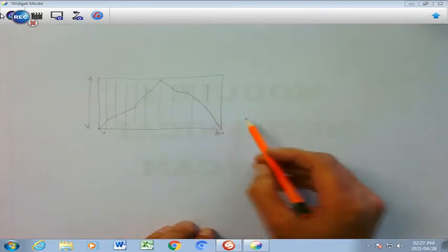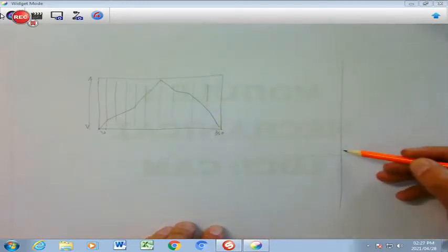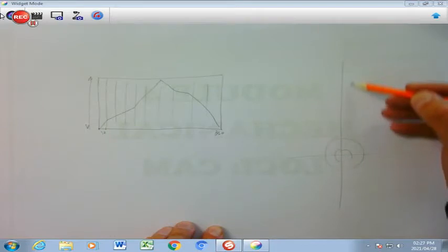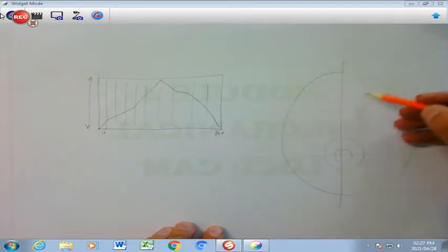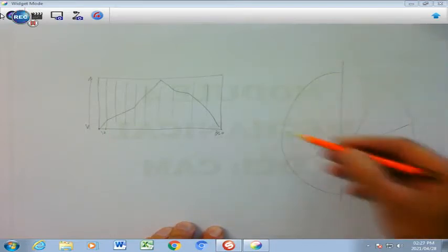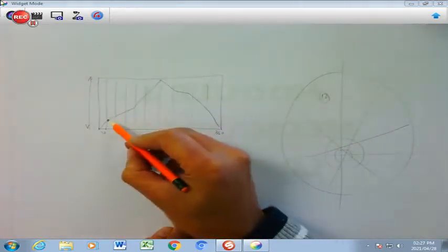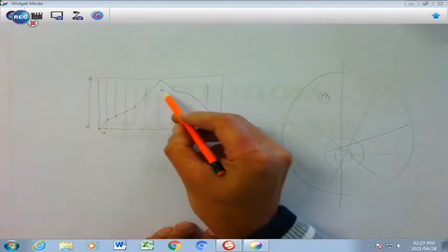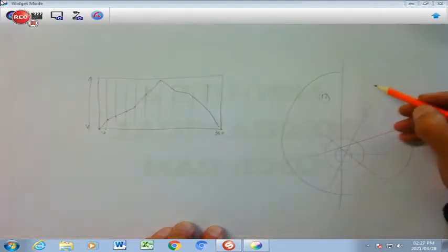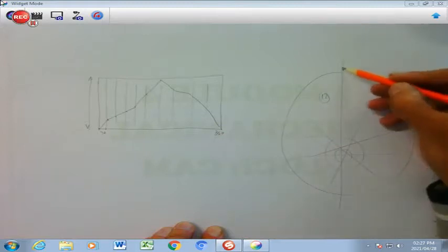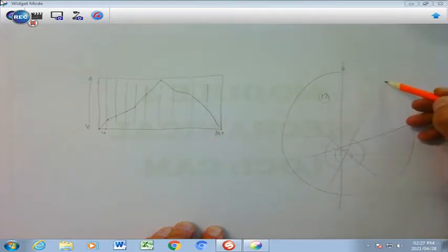Then from there you will have to draw a center point where you are going to have various circles, and you will have the divisions of the different parts also in 12 spaces. You will plot each of these straight line points onto this, with the spaces also marked as 30s, 60s, in spaces of 30 degrees right around till you get 360.